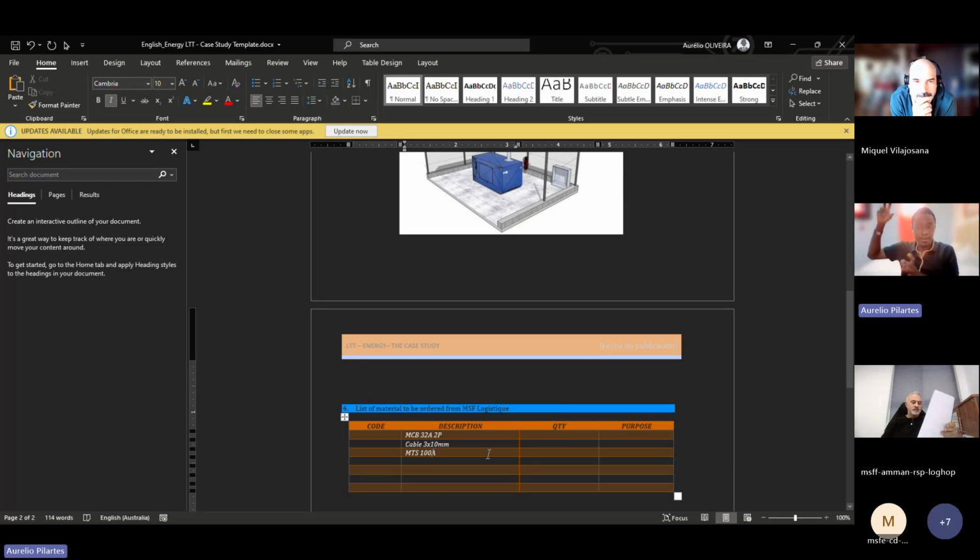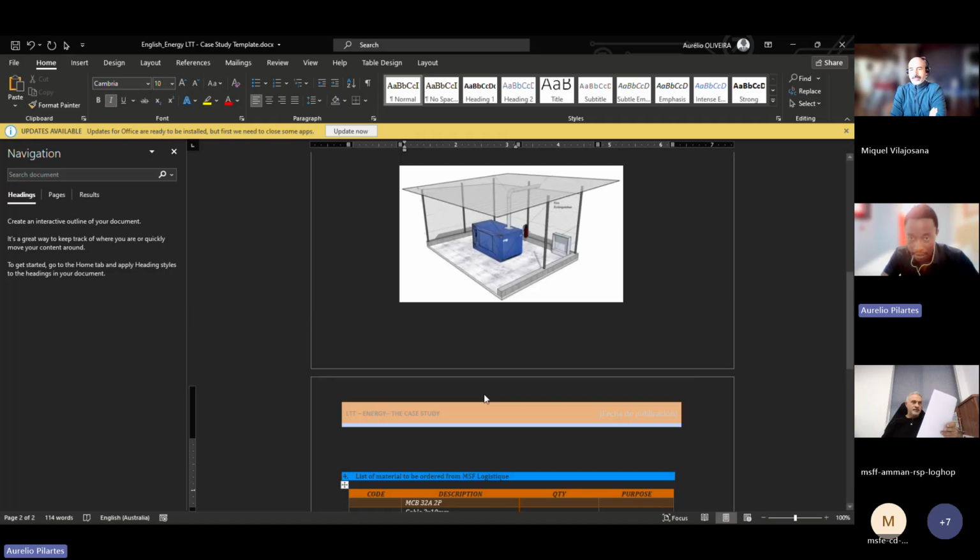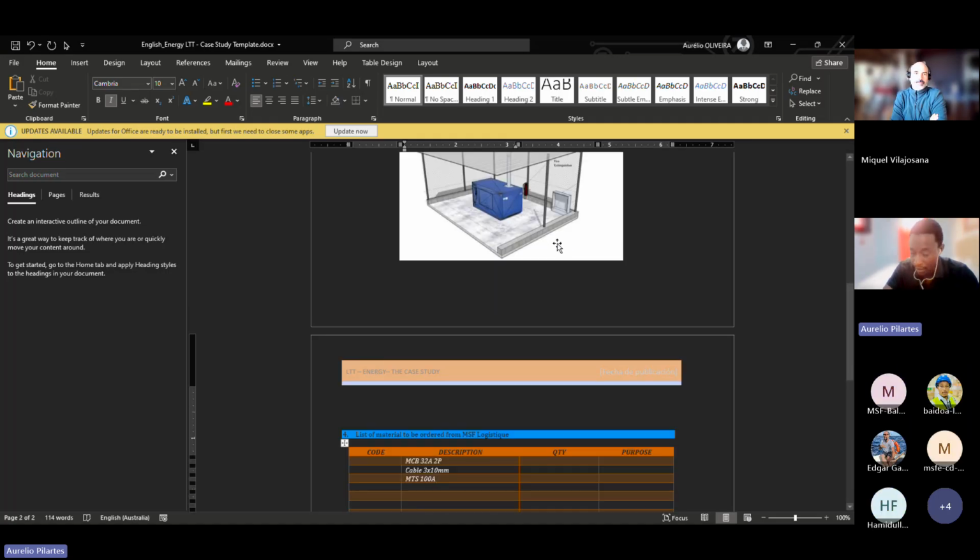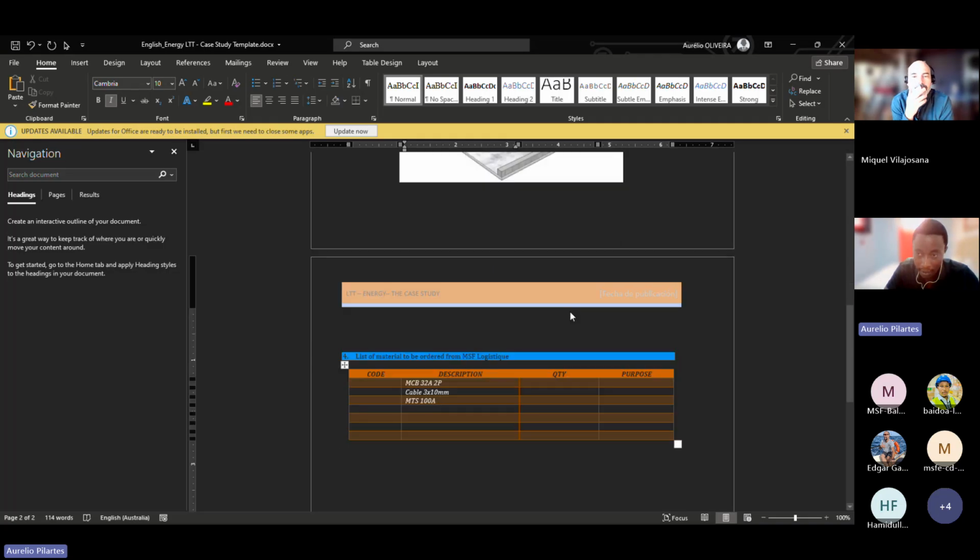Going for a bigger manual transfer switch is never a bad idea. You could have a 63 amps manual transfer switch to switch between generators, because you have two generators, the second generator being a backup.